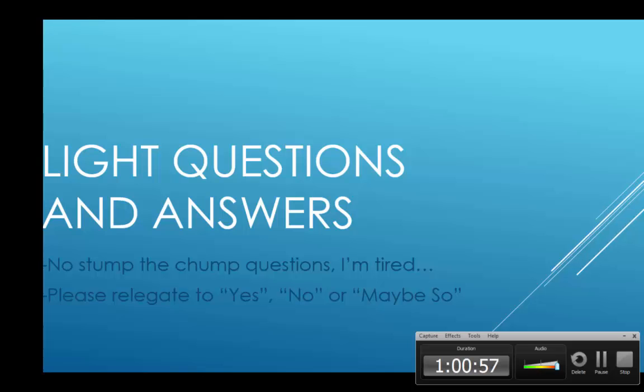They tried to do better at it, but there's also one thing that you have to be aware of. I'm not sure if everyone is, but if you're using configurations, and a lot of configurations, Microsoft has a memory leak that for some reason we happen to dovetail with. It's not something we can do on our side, it's actually a Microsoft issue, and you'll see that this memory leak basically makes your part bigger and bigger over time, and sometimes just opening the part and saving it will add 10 meg onto the file.